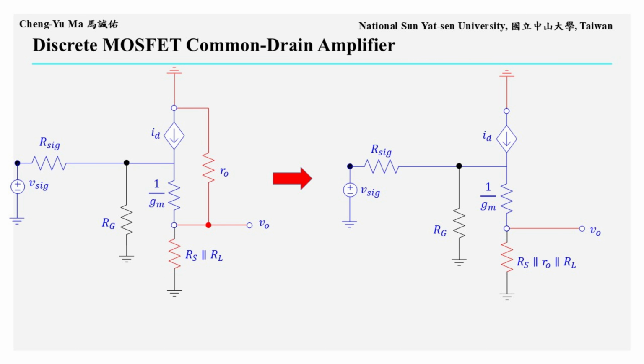We again begin by finding the input resistance, Rin. This is the same idea as in the CS circuit. Since Ig equals 0, the resistance looking into the gate terminal, Rig, is infinite. Therefore, the input resistance is Rg. Also, the source current Is equals Vin divided by the total source side resistance, which is 1 over Gm in series with the parallel combination of Rs, Ro, and Rl.